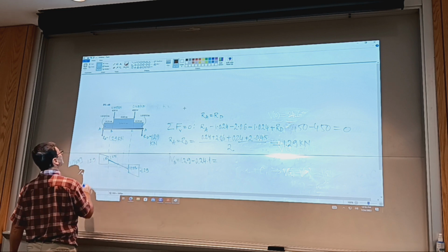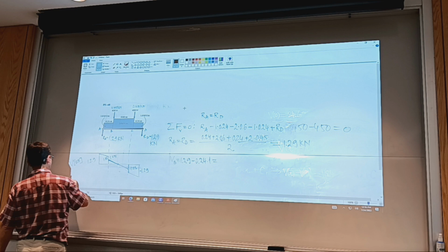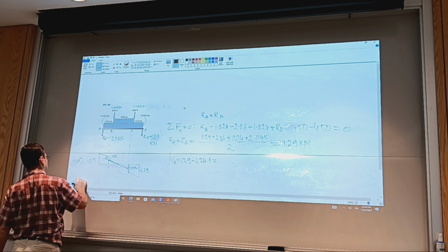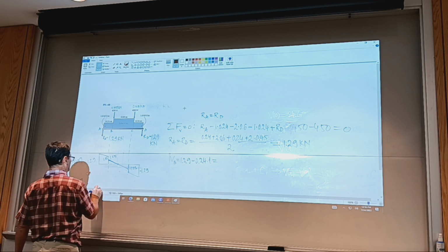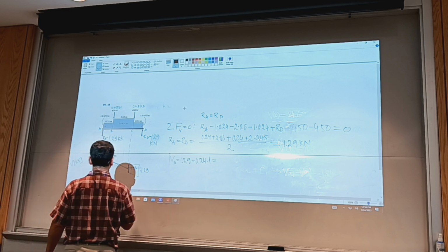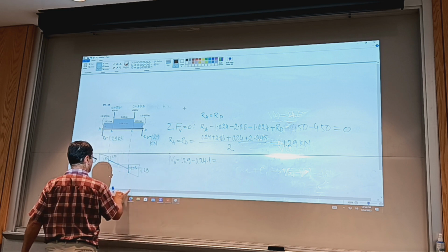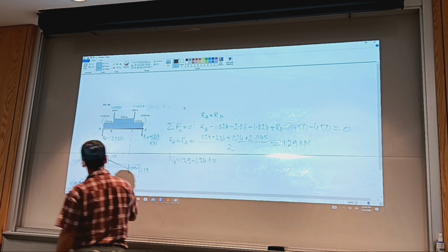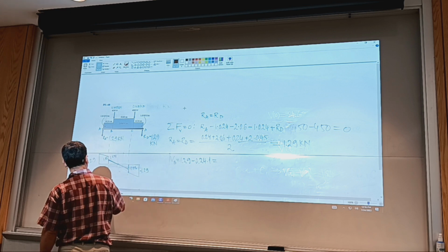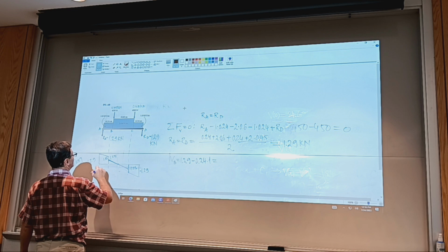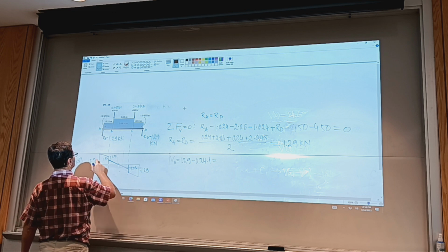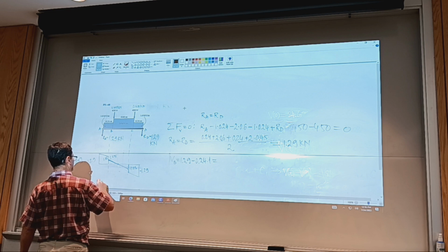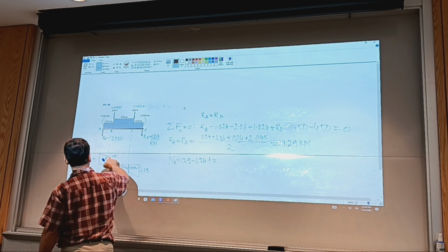And then for moments, this beam is smiling, so I know the moment diagram, in kilonewton meters, is going to be all positive. Okay, so they are parabolas, flexed at the location. Looking at the slope, it starts steeper and goes to this value here.